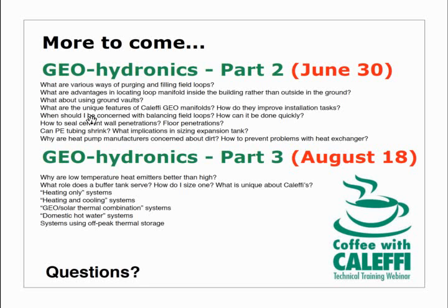Will you discuss more efficient pumping, lower wattage in the upcoming session? Yeah, we're going to touch on that some more. I think he's talking about using ECM pumps. Yeah, a lot of the schematics in Hydronics 9 do have ECM-based pumps and essentially leverage this concept of valve-based flow control in combination with a variable speed pump, both on the earth loop side and on the load side.